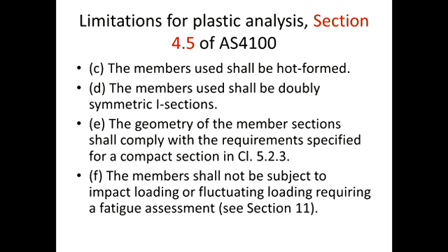Like if we look at the Australian steel market, for example, the hollow sections are mostly cold formed within the Australian market. So it means that if we are looking at hollow sections, we cannot use plastic analysis based on the standard.